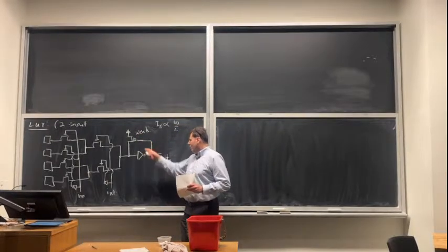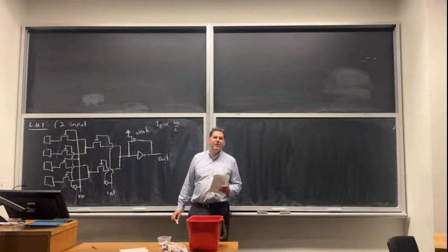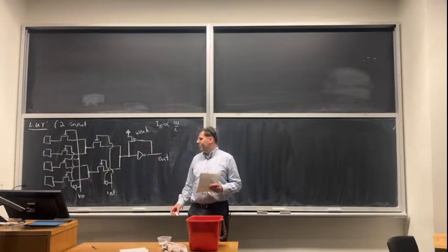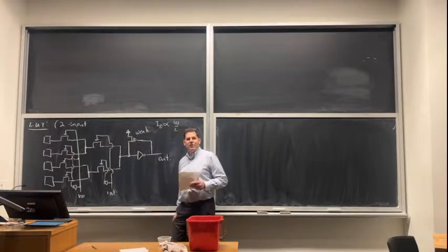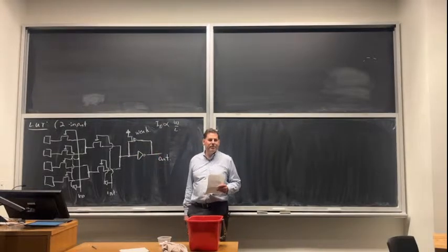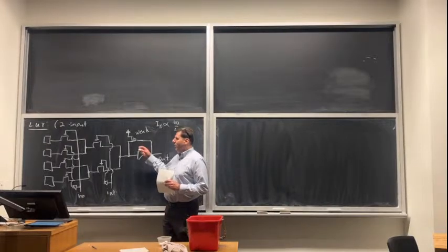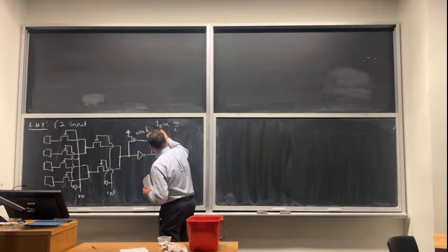Okay, what is this for? Why did I put this here? I'm going to repeat this 5 million times, so I don't really want to have any transistors that I don't need. But I need it. Yeah, what do you think? So that's reinforcing the relatively weak signal that's passing through the 2 resistances. So that's acting as like a pull-up, basically. Yeah, so this is a weak pull-up. So it is a pull-up.